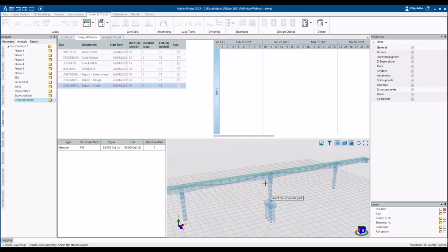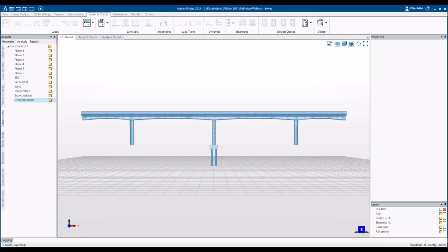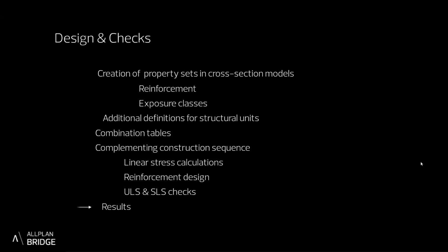The reports can also be produced on demand in the 3D model by right mouse click and selection of the required report snippet at specific stationing. By clicking on the Recalculation button, we run all geometry calculations, structural analysis, evaluations of superpositions and combination rows or groups. At the end, the complete nonlinear reinforcement design and checks are performed.